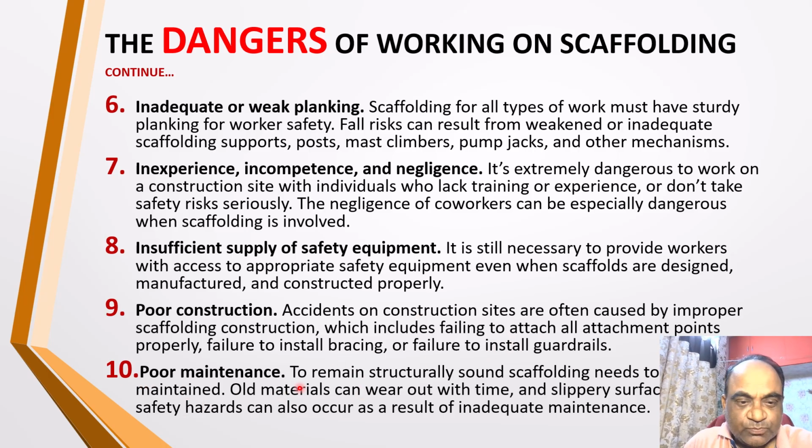Tenth point says poor maintenance. To remain structurally sound, scaffolding needs to be properly maintained. Old materials can wear out with time, and slippery surfaces and other safety hazards can also occur as the result of inadequate maintenance. So maintenance of the scaffolding materials is also very important. Otherwise, because of wear, planks could be slippery and that can cause an unsafe situation.